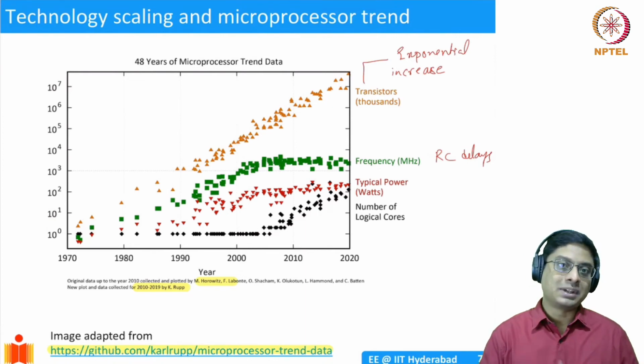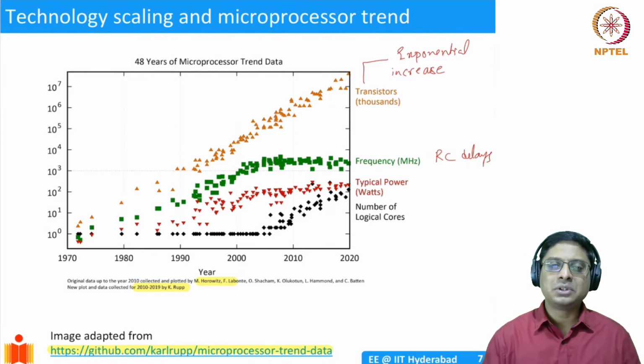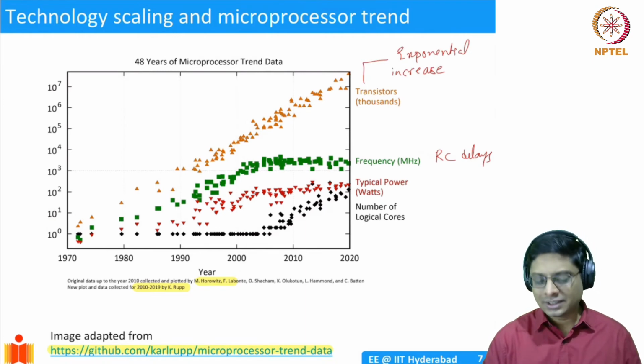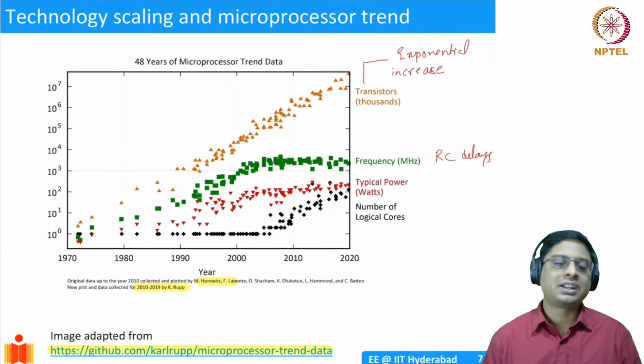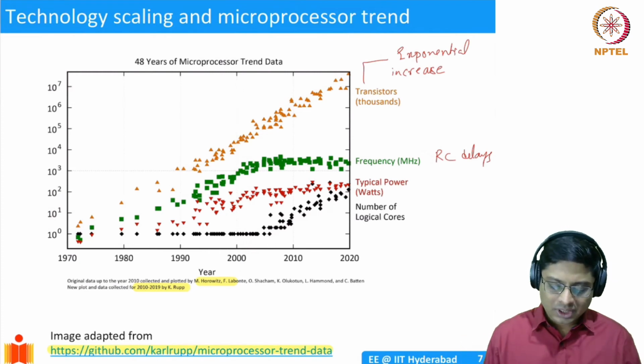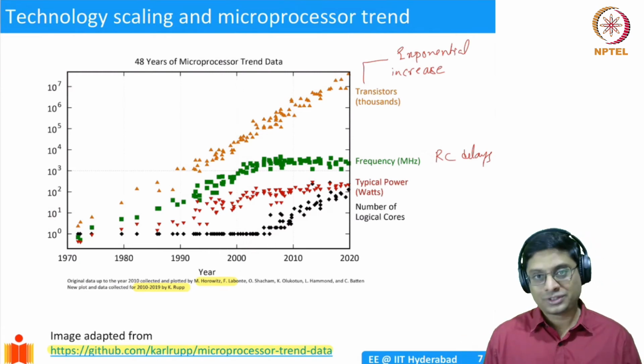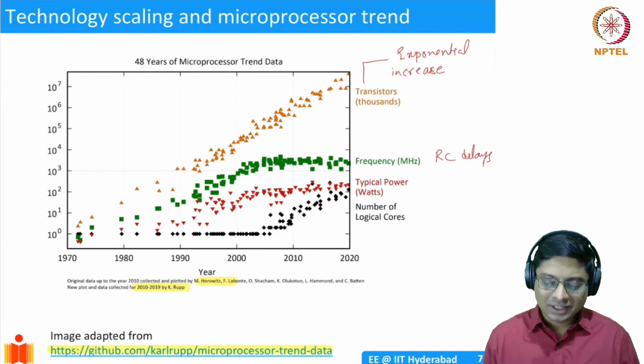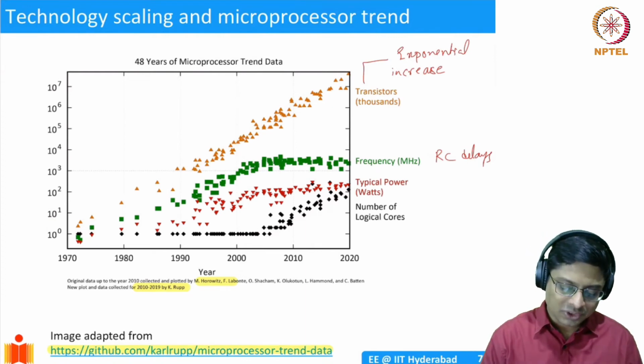In our classical scaling scheme, we saw that we are able to reduce the sizes by 30% and maintain the same power, right? Because the power dissipation was, or rather, I said, a 50% reduction in the power. So you can keep the same power and double the number of transistors, right? We wish that was true, but it turns out that practically there are many challenges in achieving it. And so what was realistically possible was this.